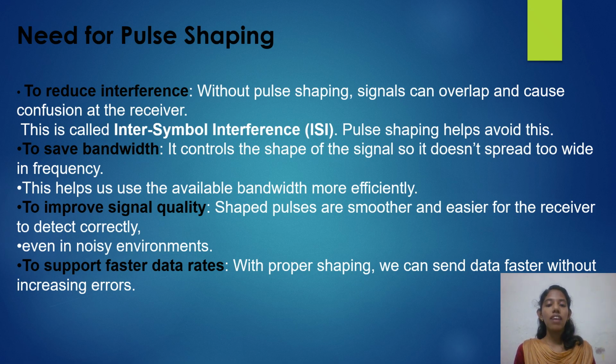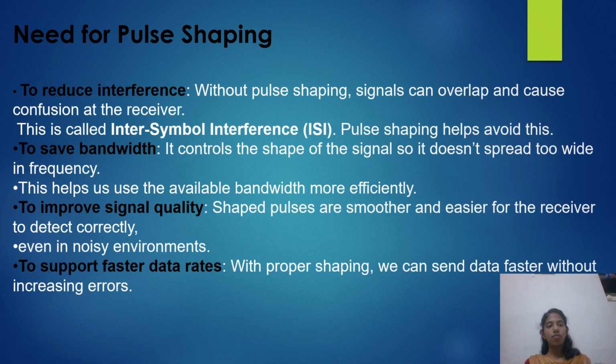To improve signal quality, shaped pulses are smoother and easier for the receiver to detect correctly, even in noisy environments. To support faster data rates, with proper shaping, we can send data faster without increasing errors.